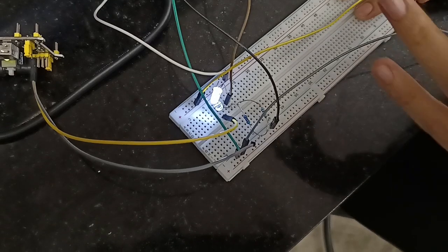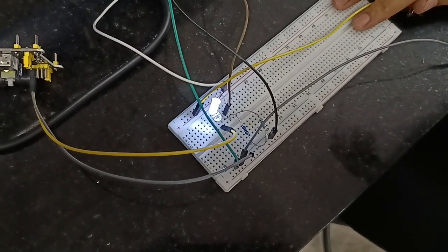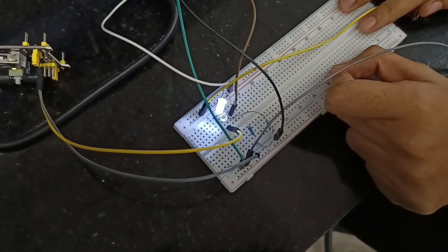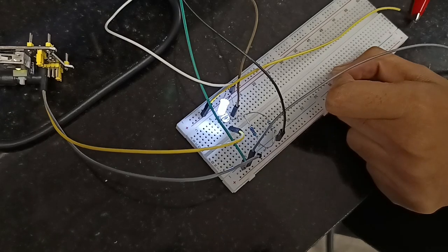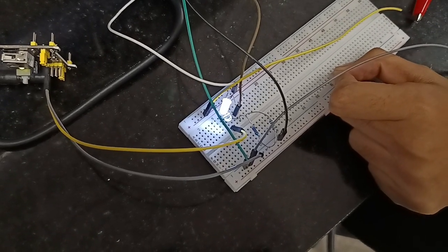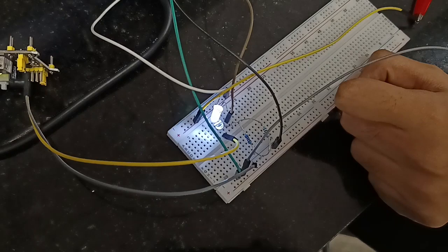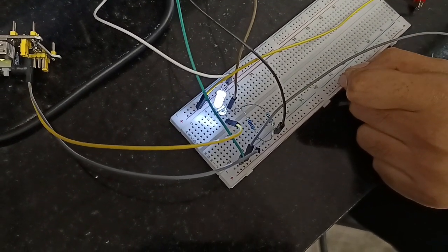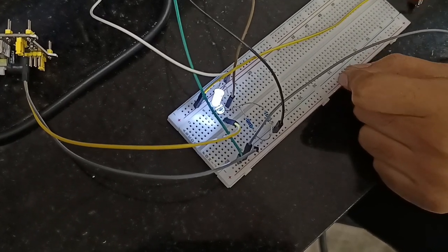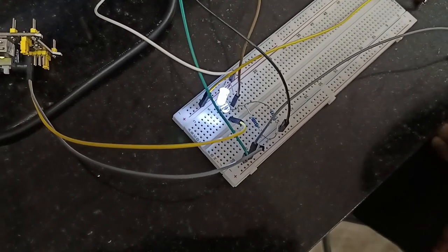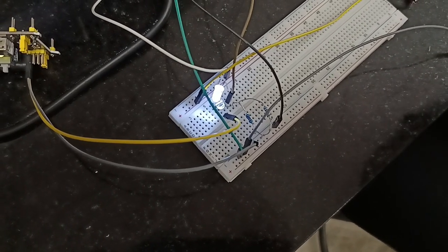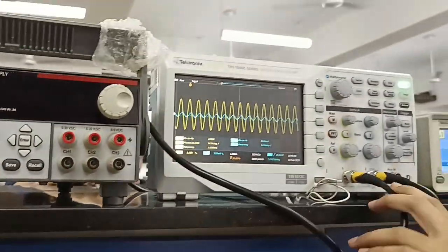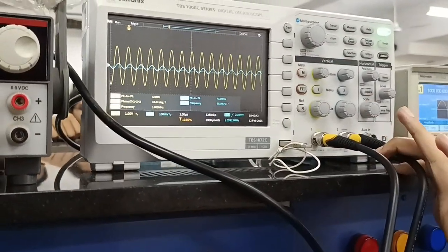Then there is another circuit, where we will give a 5 volt power supply connected to the breadboard, and the 5 volt positive terminal is connected to the negative terminal of the photodiode because it's in reverse bias. Then the positive terminal of the photodiode is connected in series with the 10 kilo ohm resistor, and the 10 kilo ohm resistor is grounded. We will measure the voltage across the 10 kilo ohm resistor through the oscilloscope. Channel 1 is input and channel 2 is output.